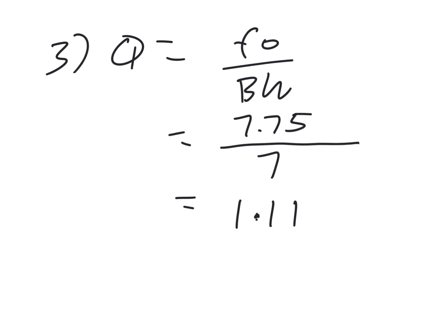Basically, as you make the filter less selective, the quality factor, the number, goes down. So as you move FC2 out, it passes a wider range of frequencies, and the filter is said to become less selective.